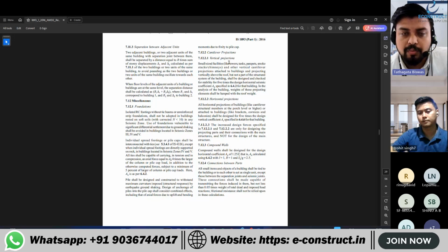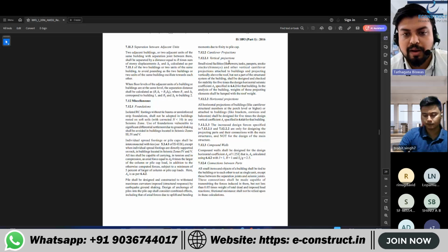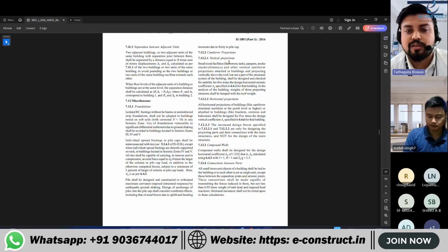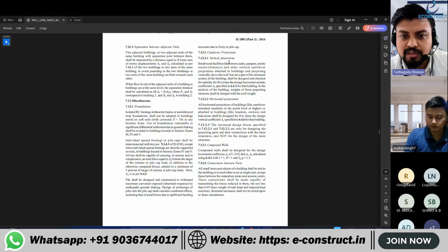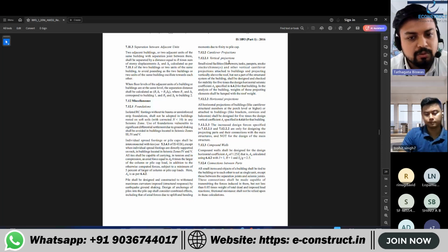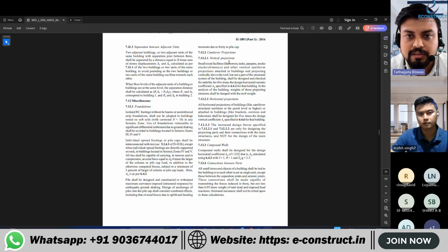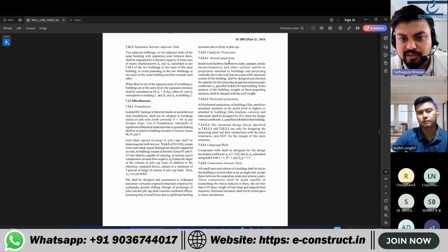So we need to check the property in our system, like in our state or in our places, what kind of brick we are using, and the different parameters for that need to be put in the user defined masonry infill parameters. Those parameters are not possible to get from the site all the time. You will not get them anywhere from any vendors, and by looking at it, it is very difficult. On the internet, you will get multiple properties for multiple different kinds of things. Because of this issue, we are not modeling the brick walls.